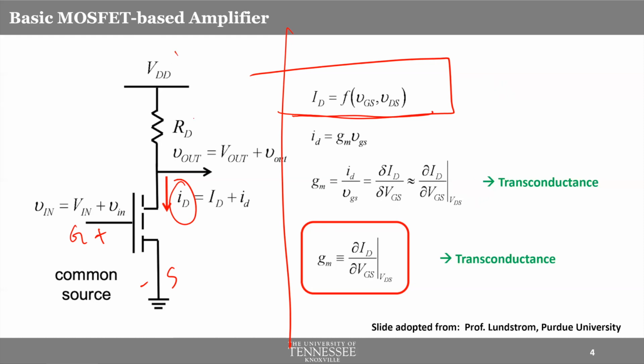Just a quick side note here, a little bit of a tangent. Even though we have applied a VDD at this end, that doesn't mean the effective VDS of the transistor will be VDD, because there will be some voltage drop across this resistor, and then the rest of the voltage will go and act like an effective VDS. Just to keep in mind, if we didn't have any resistor connected here and we just added a VDD directly, then VDS will be VDD. Okay, just a side note. Now, okay, getting back to the point.